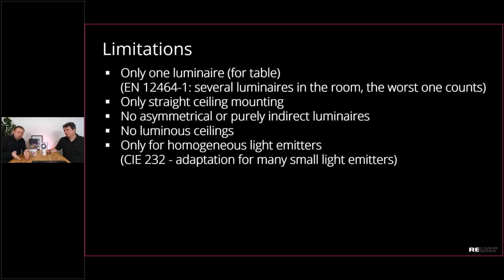It's not meant for luminaires which have a lot of tiny outputs, but there is a relatively new standard, three, four, maybe five years ago, CIE 232. This standard has an adaptation factor to deal with the situation if you have multiple small outputs in a luminaire, like LED lenses or small reflectors.